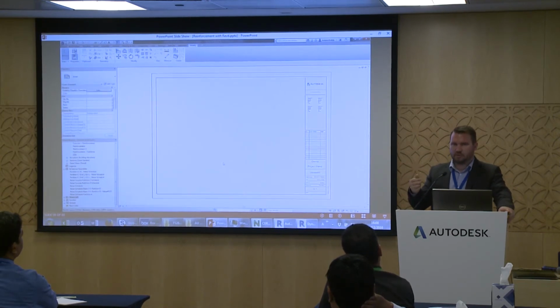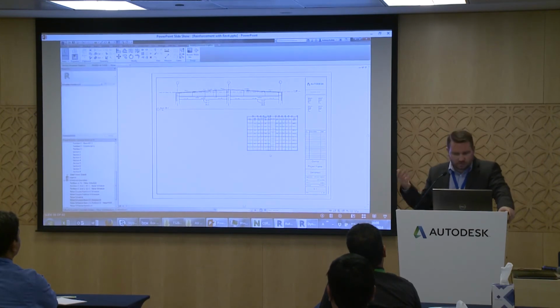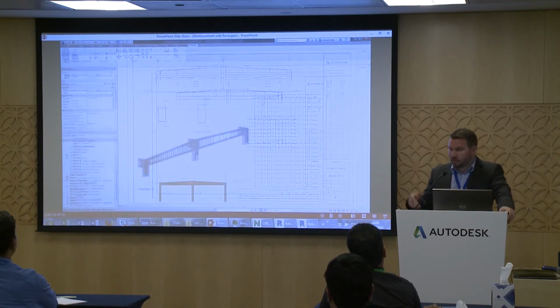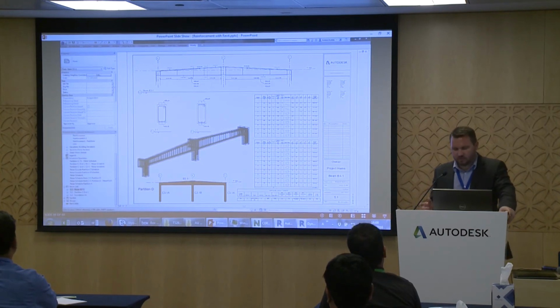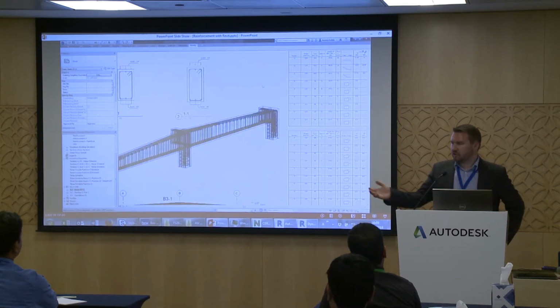Once you've done one project, you've put your tagging the way you like, etc. After, you know, it's Revit, but to adjust the classic tagging to your needs, it can, of course, like you have done in Revit for all elements, take some time, but when you have done it once, it's on your template and it doesn't create some element. After, you can, of course, import from a file to another file if you miss something, okay? And you have a classic result.